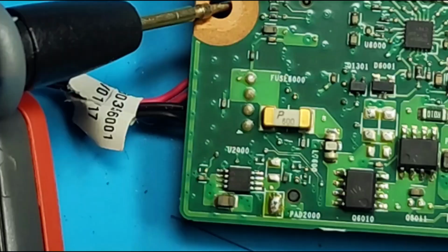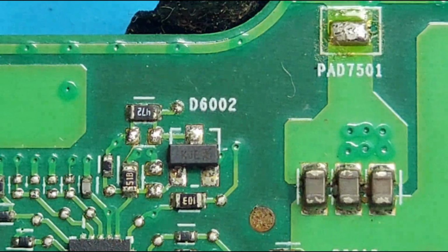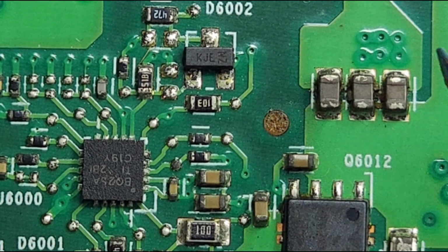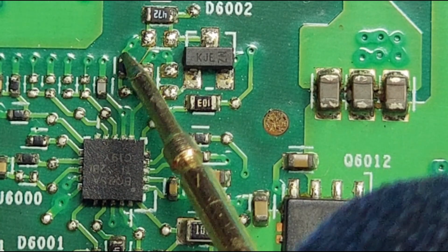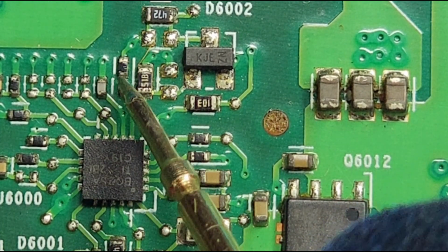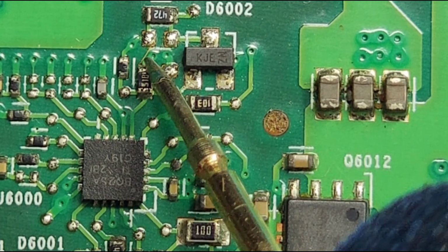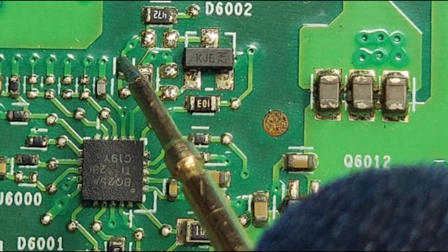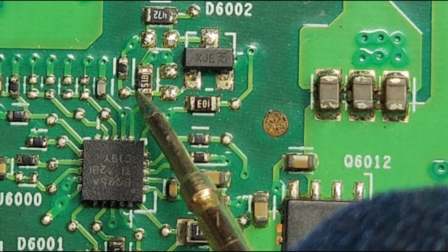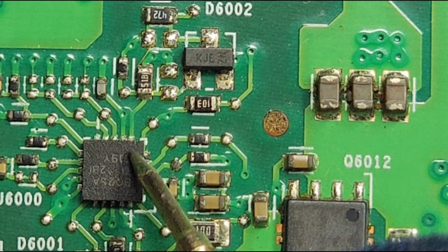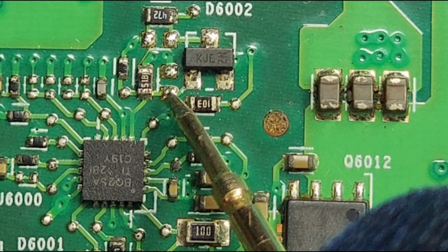Okay. So let me clarify it more clearly. Yes, so this is just a resistor divider circuit. On this side, it is connected to the adapter directly. And on this point here, we will get the divided voltage. And on this side here, it is connected to ground. So we should have an appropriate value of resistance on these resistors in order to get an appropriate value on pin number 6 within 2.4 to 3.15 volt.